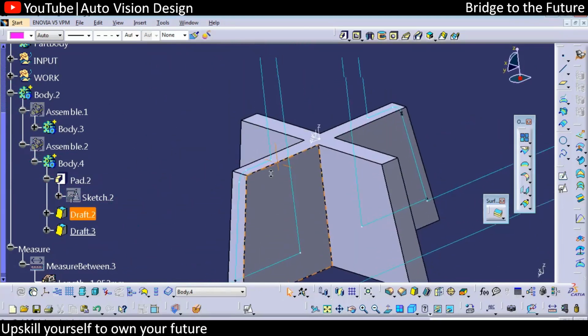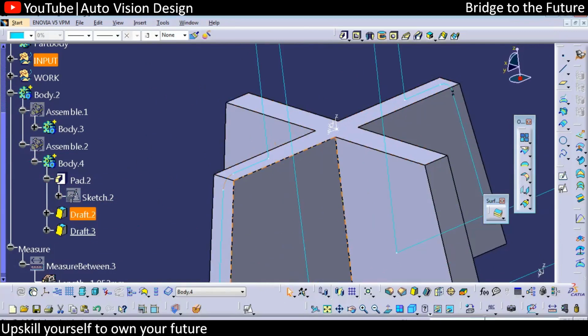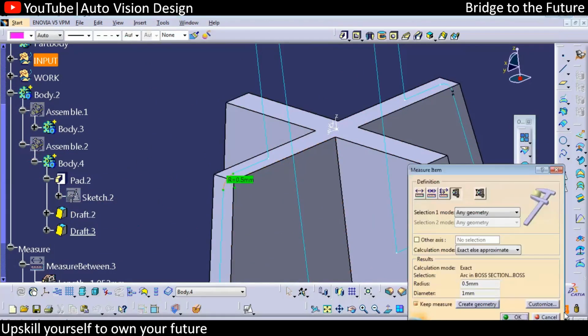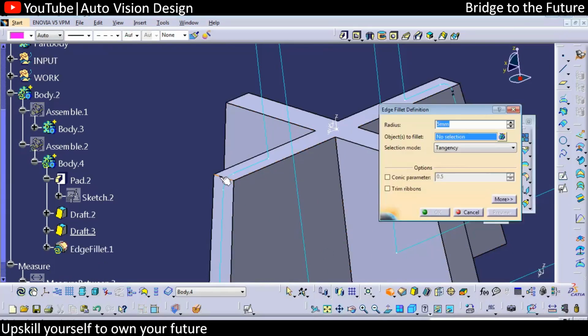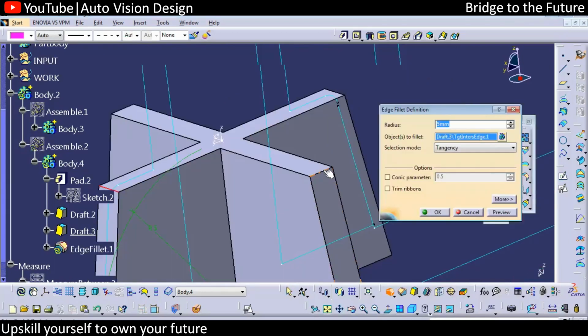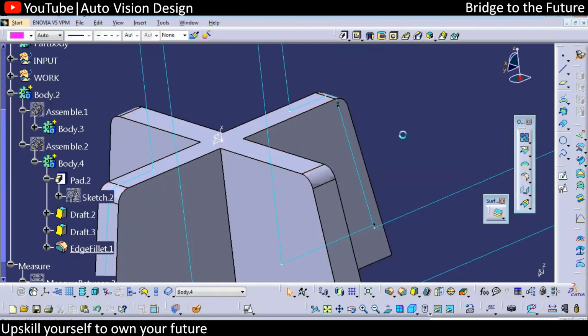Now, to avoid the sharp corner, we need to add the fillet on the rib. It is given over here in the master section. So 0.5, we will have the fillet. We can add the 0.5 fillet on all the sharp corners, whatever is available. So this is something we can add.